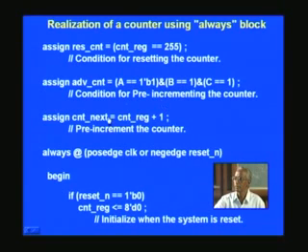What we need to do is, we have to increment the counter register. That is the output of the counter, which we have already seen. Just increment by 1. Note that there's no need for 1 stroke B and so on, so it can be a plain decimal number as such. And so the incremented value is assigned as the next value for the counter. Only this is a pre-increment thing. Actually, it increments beforehand, and the incremented value will be assigned or not assigned depending upon the conditions inside the always block.